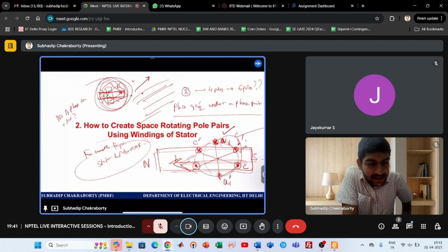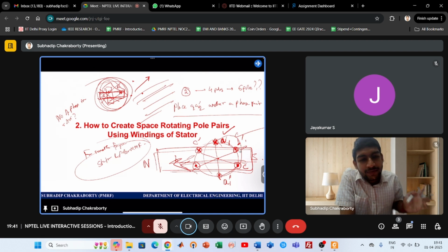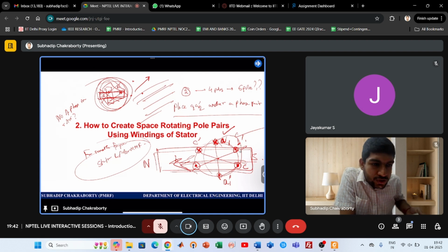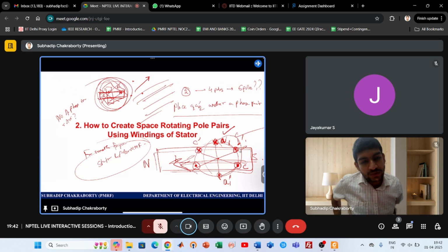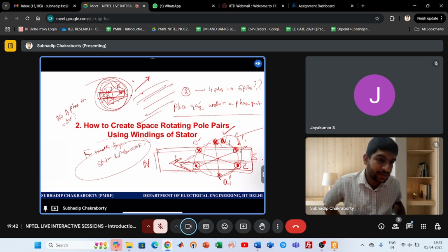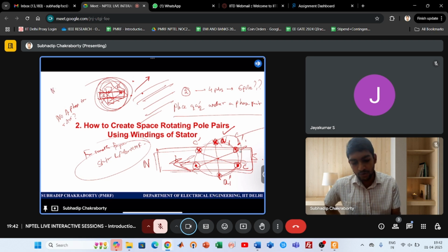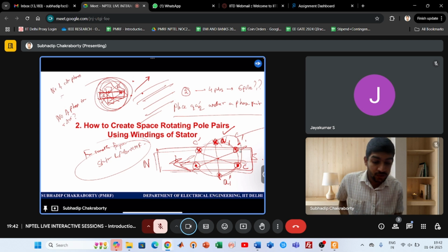Even you can take a polyphase induction machine and, making the winding connection somehow, create maybe 6 poles. We just talked about how. And the rotor will also adjust itself to 6 poles, and smooth torque, smooth rotation will be achieved. But you still don't know the number of phases of the rotor, and I can guarantee you that there is no such constraint that the number of phases of the stator and rotor should be the same. In this case, you know how the rotor phases will be. The number of rotor phases, just give it a thought, will be equal to the number of slots per pole.